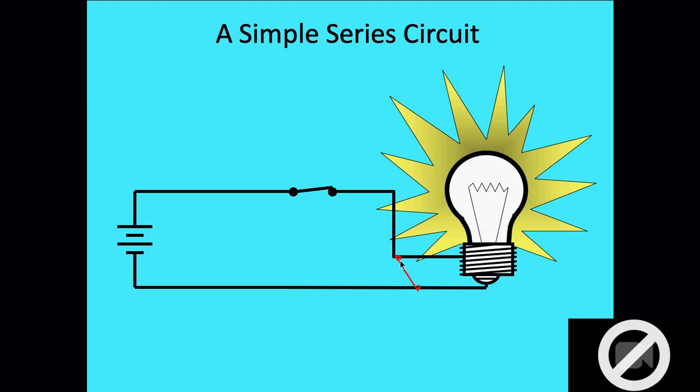Okay? I ask these what's an outcome questions for a reason, because that's where we start to learn about troubleshooting. If you come up to a property which has a blown fuse or a blown breaker, I normally try to reset the breaker after making sure no one's touching the equipment while I'm doing that. But fuse, you want to find out why we have a blown fuse. We don't just replace the fuse and let it blow again over and over and hope that somewhere some inspirational force will come down and fix it for you. We have to find where my short circuit is.